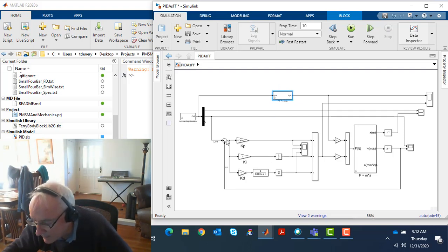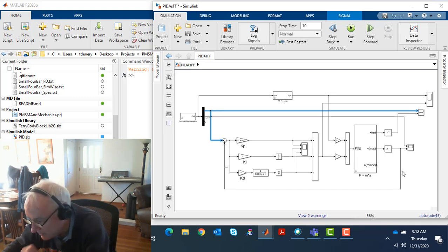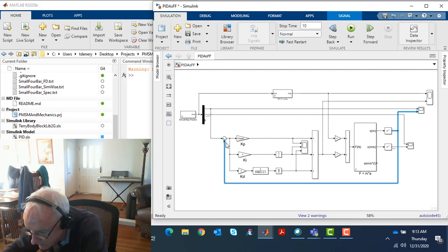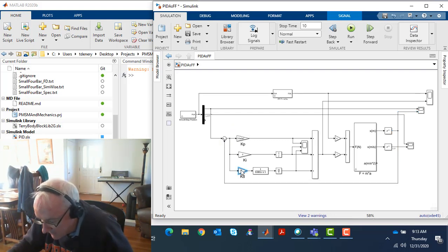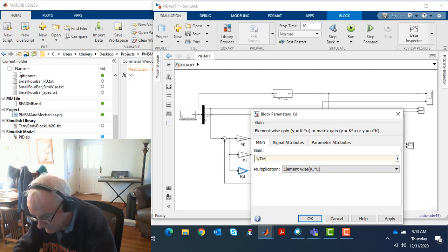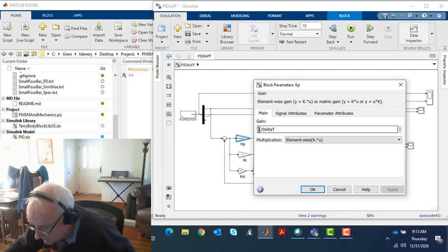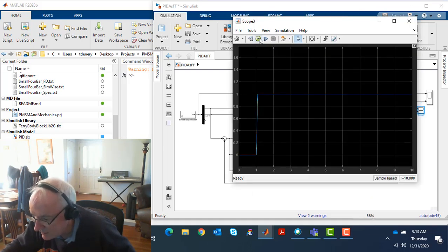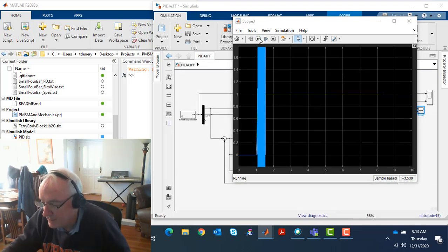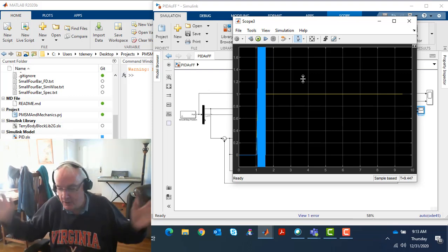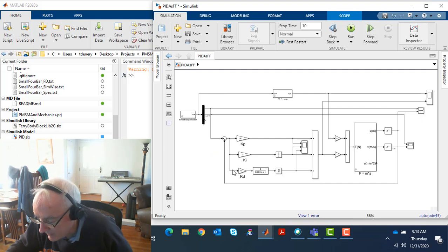is the idea that, well, why don't I do it with position control, all right? And so I'm going to take position now, and I'm going to feed back position here, and now I'm going to make my KD 1 over delta T. Okay, and I'm going to zero out my KP. And I'm going to hit run, and all, I won't say, I'm afraid I'm going to use a cuss word, but let me say all heck breaks loose. Okay, and I'm going to just say it doesn't work,